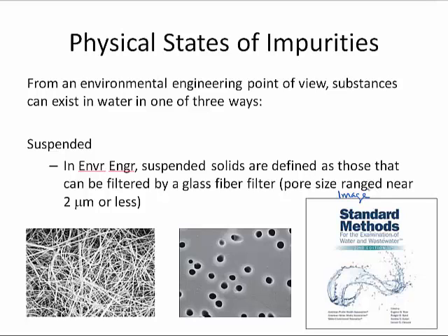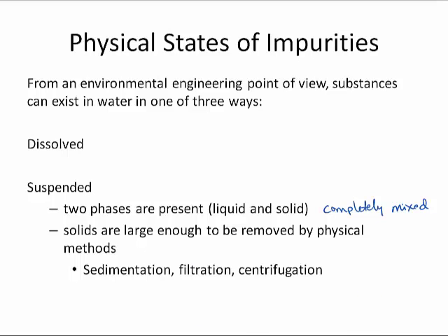So just to summarize, suspended solids are physically defined as when a solid is suspended in a liquid phase. In environmental engineering, we have an explicit definition which is defined in the laboratory through filtration of glass fiber filters. From a treatment perspective, to remove suspended impurities, we will see that sedimentation is extremely prevalent because it uses only gravity, and gravity is free and very cheap to implement if you have the space allowable. Sedimentation is one of the key process units used to remove suspended particles.